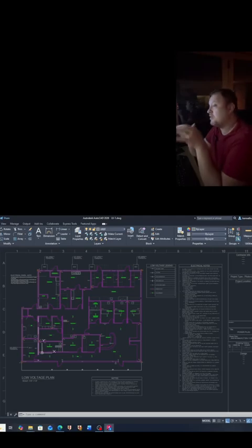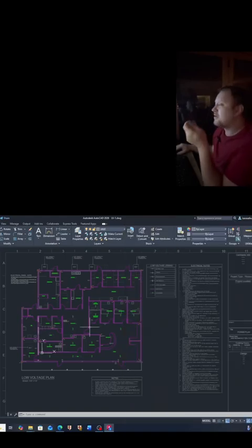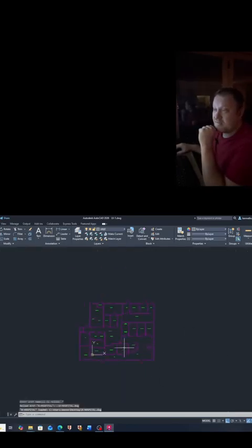And then again, when they make a change and hit save, everyone's machine that's working on this project, there may be guys doing the low voltage, there may be guys doing the electrical, guys doing the mechanical, whoever's doing what in the company. An XREF change happens, you'll see this message, you just hit reload, and then now it reflects the change that we have.